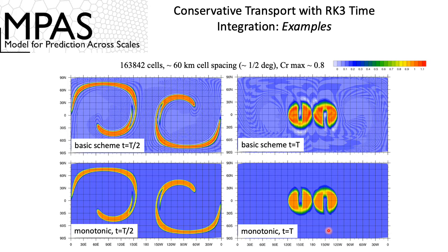They're not perfect. Of course, the initial conditions are slotted cylinders where the concentrations go from 1 to 0 across one cell length. So it is a discontinuity. These are discontinuous slotted cylinders on the mesh. Not going to be perfect. There are going to be some overshoots and undershoots, but as you can see, the solutions are very clean and very good looking, and all this waviness away from the significant parts of the solution, where the significant concentration should be, is gone.